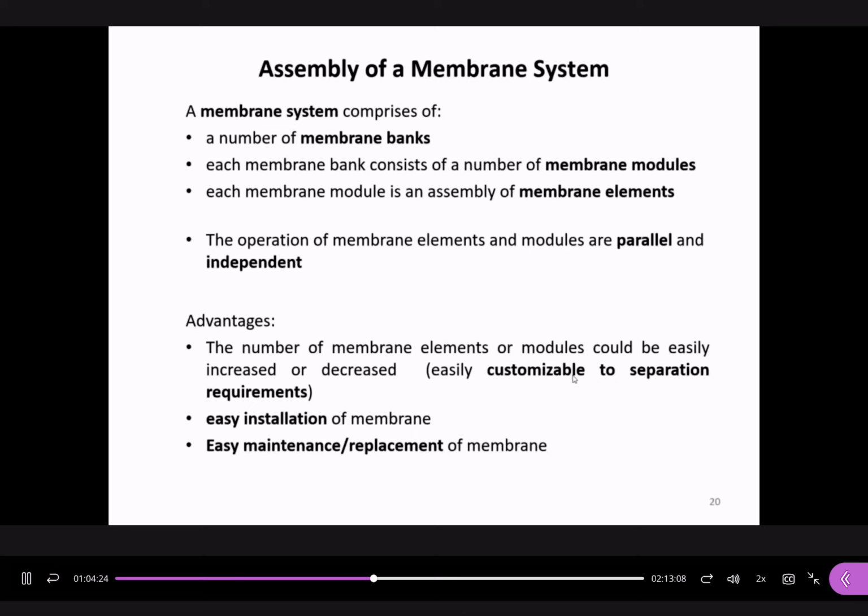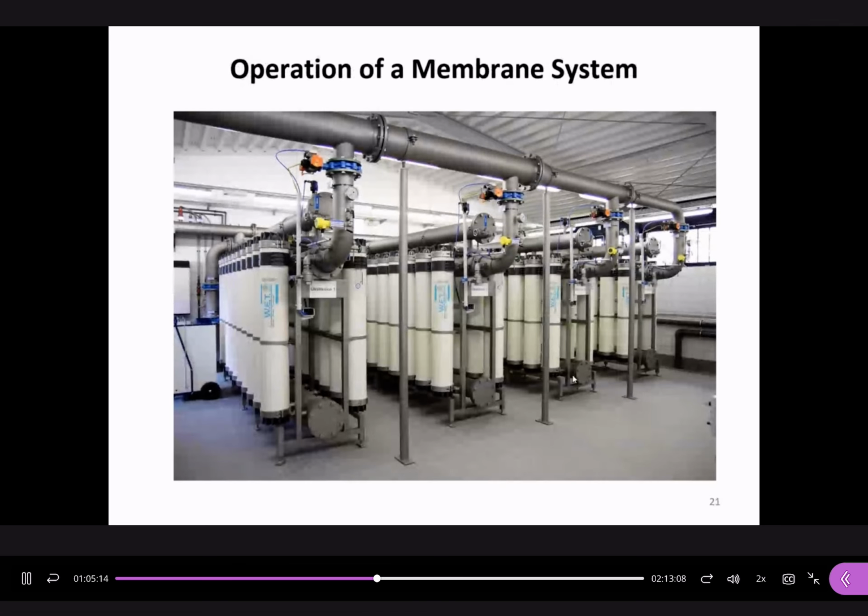All right. I shared one article with you, uploaded in the Blackboard. It's about the TKO desalination plant. Please read the article. You can find from the article that installation of the RO membranes at the TKO desalination plant was completed within 10 days because it had already been pre-assembled. So there is easy installation and easy maintenance and replacement of membrane modules. If one module fails to function, you can replace that. This is the actual system. Look at this. Of course, you have different configurations, different heights, different diameters, which suggests different filtration areas or different water production capacity.